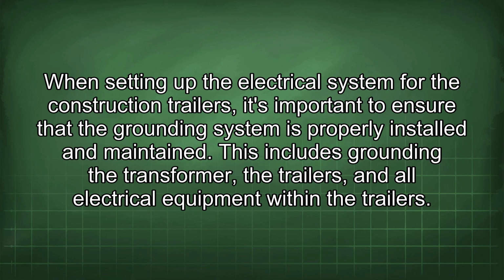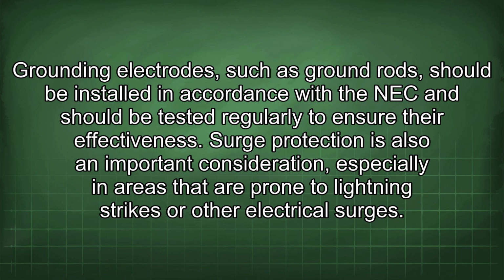This includes grounding the transformer, the trailers, and all electrical equipment within the trailers. Grounding electrodes, such as ground rods, should be installed in accordance with the NEC and should be tested regularly to ensure their effectiveness.